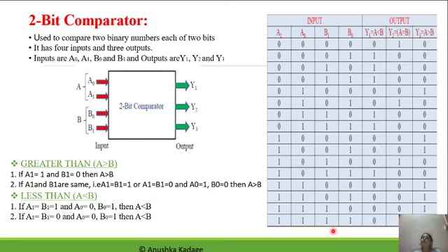So, is it clear, friends, how to write down the input combinations for the 2-bit comparator? We know each number is a 2-bit combination, so the possible combinations will be 4. So the 4 combinations of A have to be applied individually with the 4 possible variations of the 2 bits of B, and that's why in total we are going to observe 16 possible input combinations.